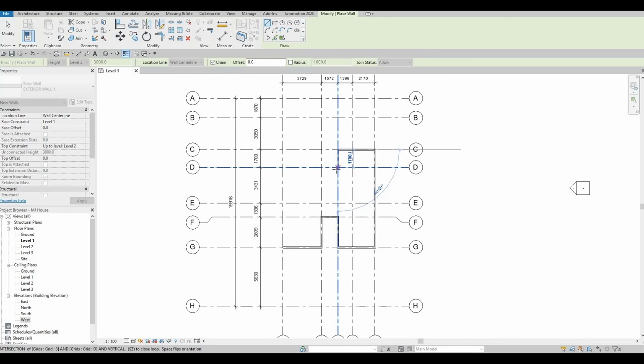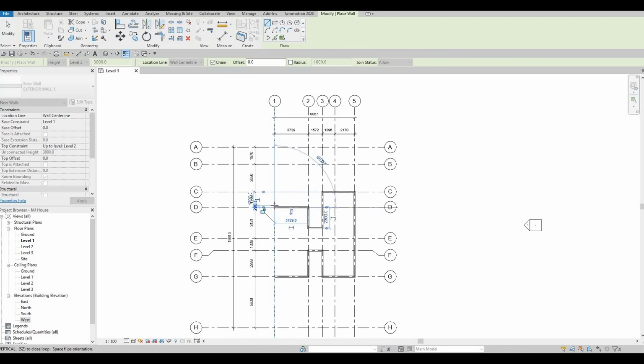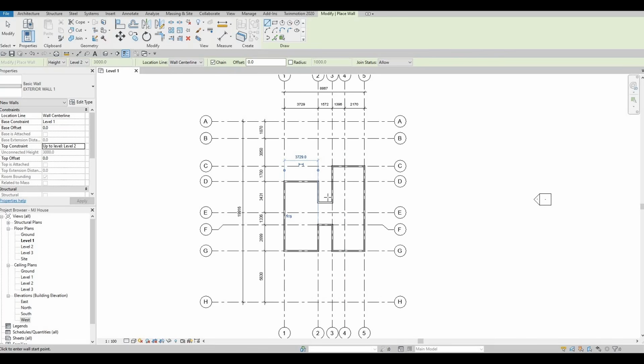So here I'm going to set up how far it will go. I'm just going to put it at 4,000. So from C3, type in going down to 4,000. And then going across this grid number 2, and then going up to D2, and then we need to go across again to D1, and then going down to G1. So this is our model. This is how it looks like.